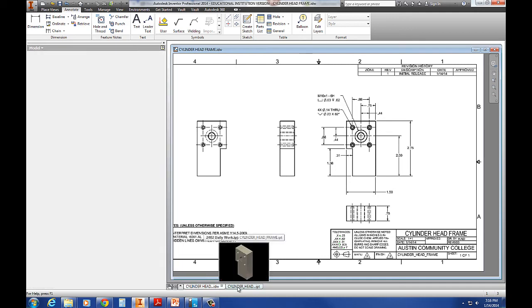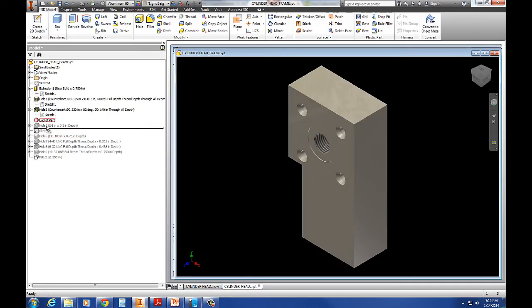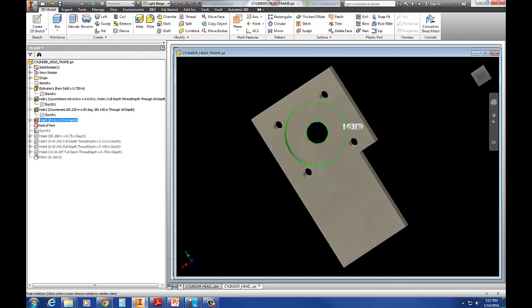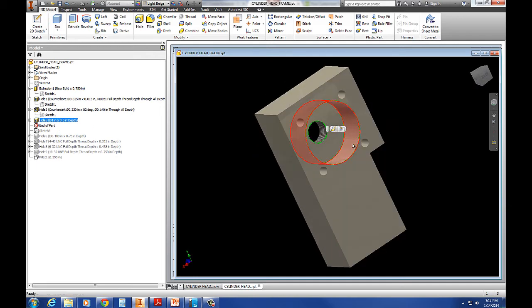So you guys got the idea here? Now I'm going to extend down the next part. And where is that hole? That hole is a huge flat bottom hole on the back. Now if you called out a hole and you called out a blind depth and I used a 118-degree tip, it's going to blow through that thread, isn't it? So what we do with a flat bottom hole is we call it out as a counterbore, so that they know that they're going to use a flat end mill.